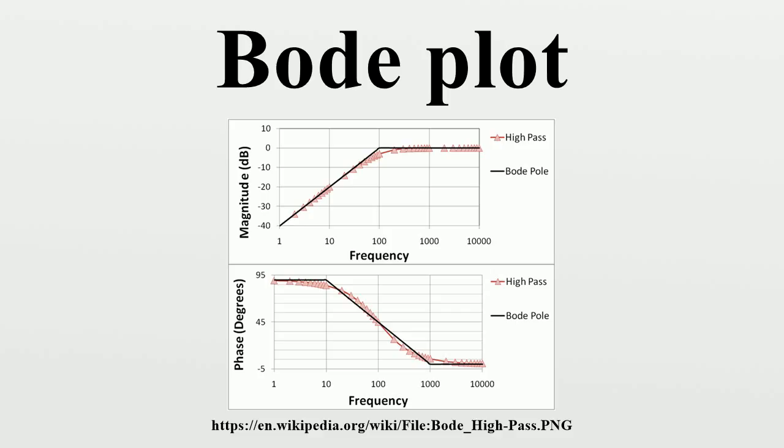Figure 4 and Figure 5 show how superposition of a pole and zero plot is done. The Bode straight-line plots again are compared with the exact plots. The zero has been moved to higher frequency than the pole to make a more interesting example. Notice in Figure 4 that the 20 decibels per decade drop of the pole is arrested by the 20 decibels per decade rise of the zero, resulting in a horizontal magnitude plot for frequencies above the zero location.